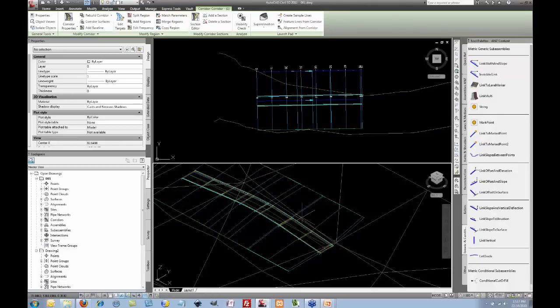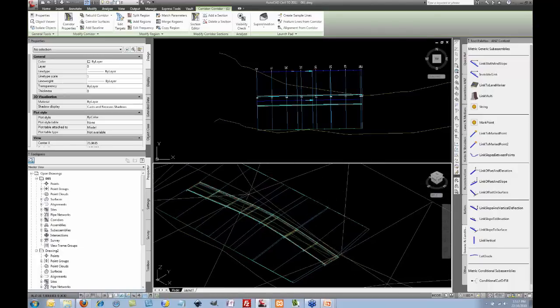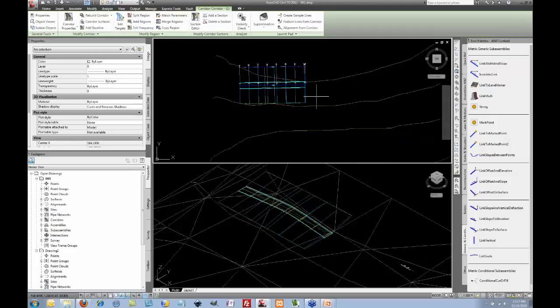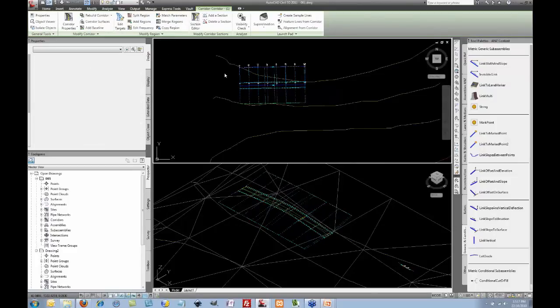With feature lines, what you could do is, after you've done that, do a typical cross-section and drape each component onto the relevant string. And the benefit then is that you get proper cross-sections and everything. So we'll show that a little bit later on. So first of all, that's the first message. You can just pin things onto natural surface. Now, let's do something more ambitious.